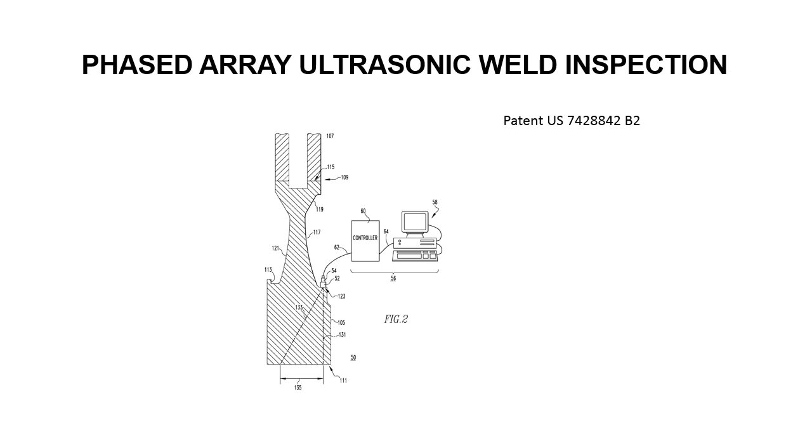Due to the possibility to control parameters such as beam angle and focal distance, this method is very efficient regarding defect detection and speed of testing. Apart from detecting flaws in components, phased array can also be used for wall thickness measurements in conjunction with corrosion testing. Phased array can be used for the following industrial purposes: inspection of welds, thickness measurements, corrosion inspection, and flaw detection.